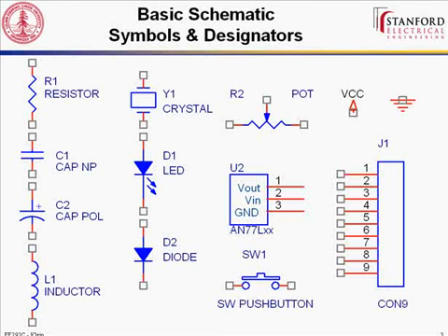It won't work. So polarized capacitors you typically can find in much higher capacitances. So for example, on our boards, you'll be using probably some 10 or 20 or even 100 microfarad capacitors there. Those are going to be polarized. Those are going to be tantalum. The non-polarized capacitors are much smaller. They're going to be like 1 microfarad, 0.1 microfarad, 0.01, something on that order. And those you can think of as being much faster at supplying current than these tantalums. They have a much lower equivalent series resistance, so they're faster for high speed.